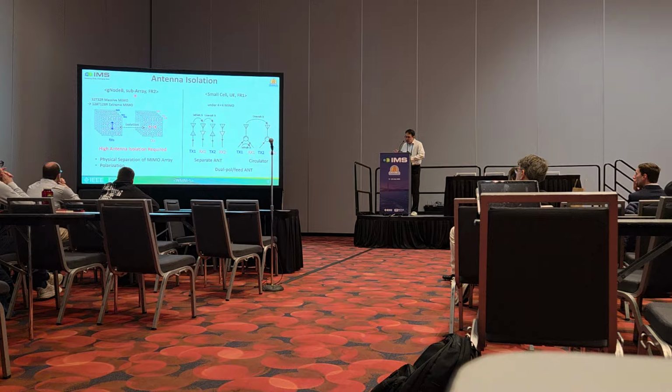For 5G, we have up to 32T, 32R massive MIMO systems, and people are talking about 128T, 128R extreme MIMO systems. So we're going to have a huge aperture for TX and RX. In this case, we can separate these two apertures to achieve high isolation. We may also be able to use the polarization difference between the two apertures.